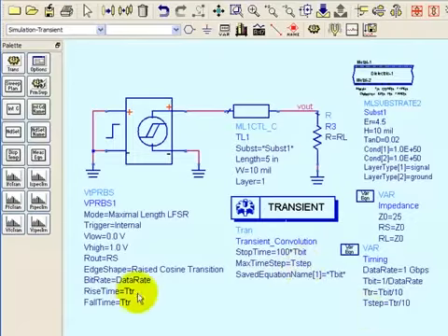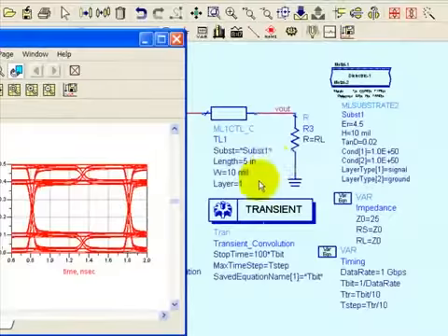So if we think about the rise and the fall time, we simply take that variable, divide it by 10, and that's enough sample rate, fast enough to accurately capture our rise and fall time for our bits. And finally, I want to save this variable in case I want to use it in the data display. And so now we can run the tuner for this simulation.